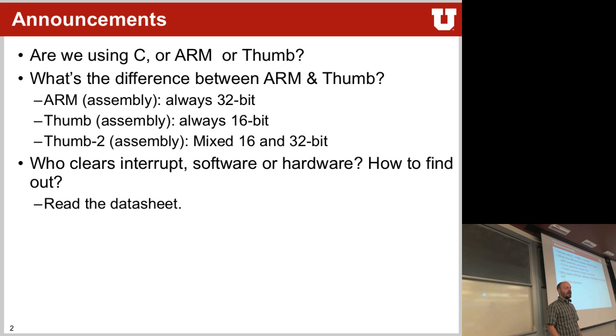So for example, in Thumb 2, if I'm not wrong, there is a divide, and the Cortex M3 does not have a divider. Now the Cortex M4 has a divider. So some functions won't work, others will. What will happen is, if you tell the assembler to assemble something for a specific architecture, so Cortex M3, and you use assembly functions that don't exist on that architecture, it will throw you an error telling you that this does not exist on the architecture itself.